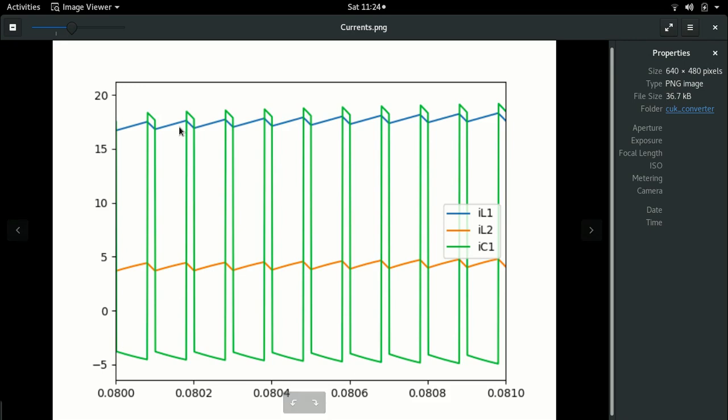The reason is simple, because you are now charging your input current to a much larger DC value as opposed to the capacitor maintaining this current through the output inductor, right? This is the decoupling effect that you see. First, the input voltage charges your inductor current. Your inductor current charges your capacitor. Your capacitor then charges the output inductor. This is how the circuit is decoupled. This is why you see this decoupling effect in which there are two different inductors, right?